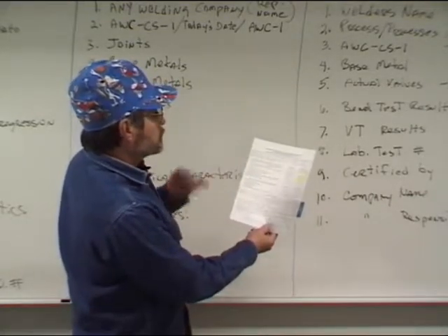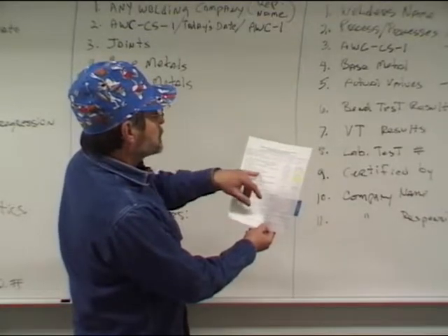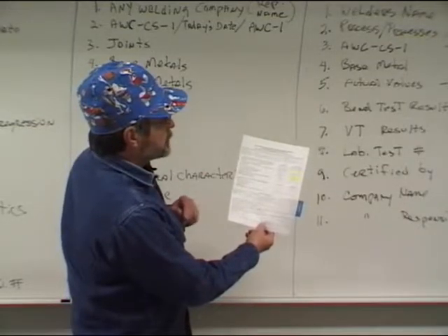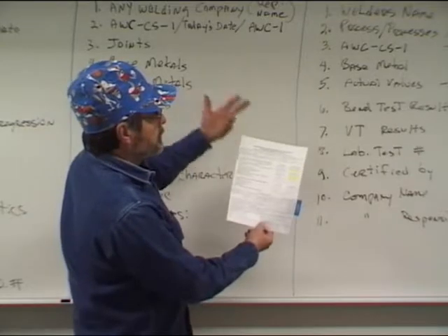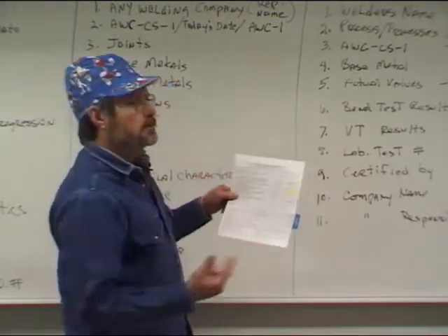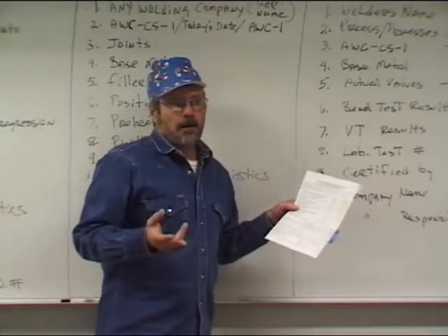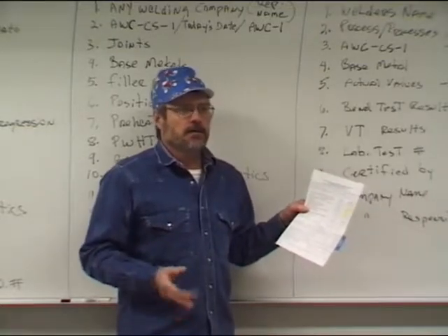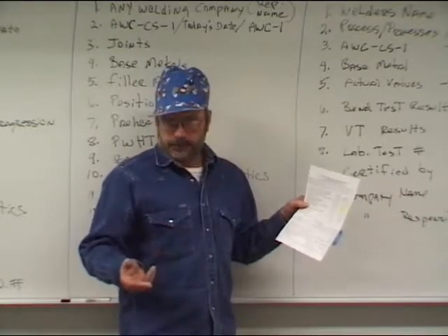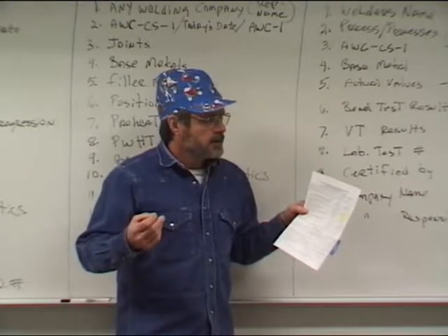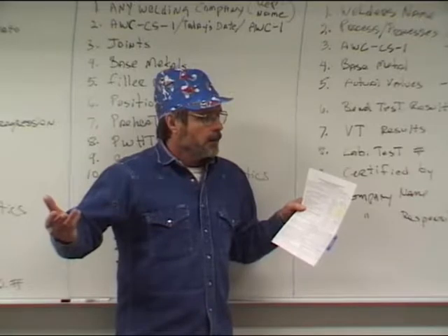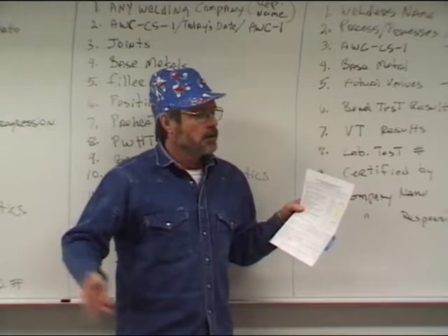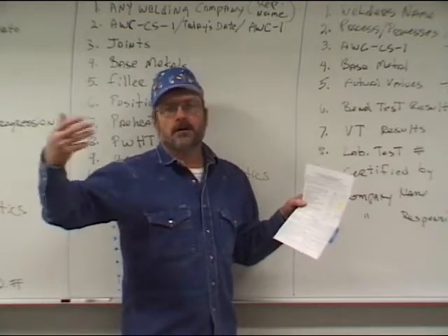Then consumable inserts, well, that's not applicable. Weld deposit thicknesses, well, we discussed that earlier, 0.125 and 0.307 for our root pass, and then our filler and our cap, and that qualifies the welder for twice that thickness. So if a welder puts a root pass in with 6010 and that root pass is 1/8 of an inch thick, they're qualified to weld 6010 up to 1/4 of an inch thick. With the 7018, if they weld the remainder of that, they're qualified to weld .307 thickness, or about 3/8 of an inch, with 7018. So now they're qualified to weld twice that thickness.